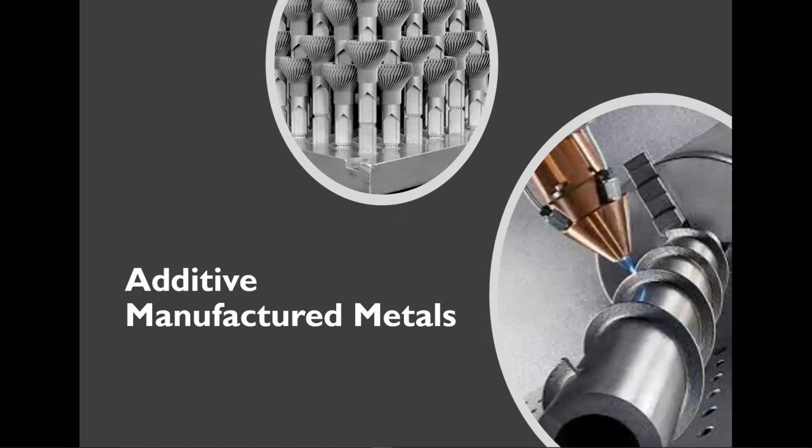However, these AM materials have been proven by literature and studies to not stand up to their as-wrought counterparts of similar composition. And actually, recent studies in literature have shown that the AM metals have a lower fatigue life and, surprisingly, an increased yield strength as compared to their similar composition as-wrought metals.